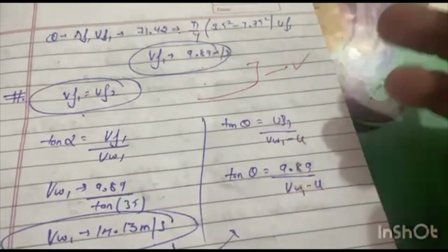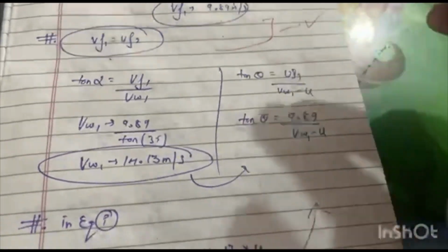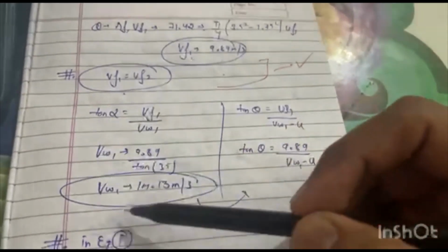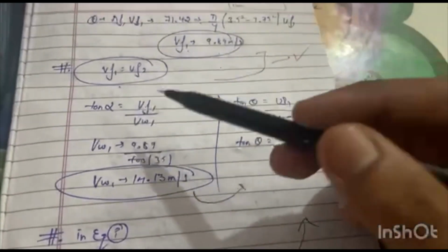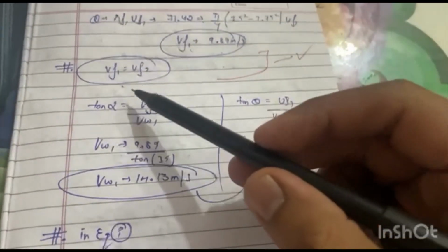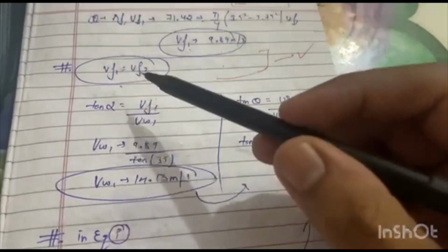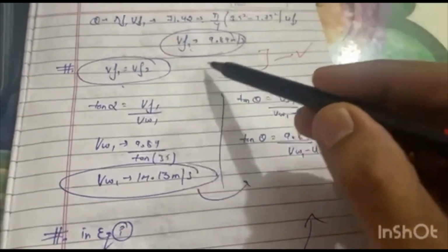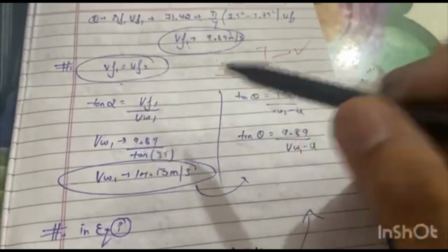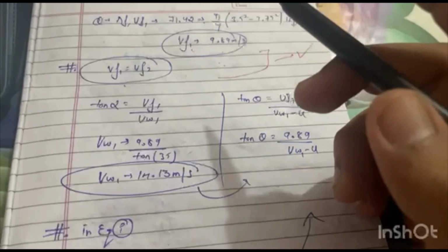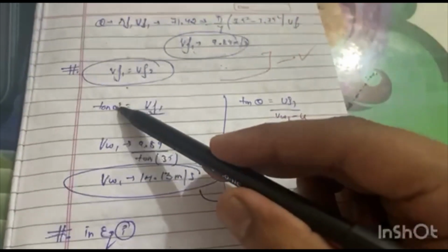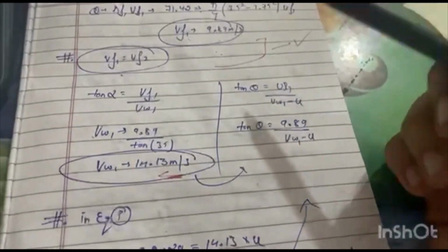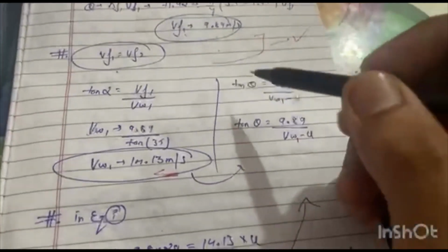अब VF1 आ गया तो हम इनलेट एंगल पे रख देंगे। वहां से हम निकाल लेंगे VW1, tan अल्फा लगा के, VF1 अपॉन VW1, हमने यहाँ से निकाल लिया। VW1 हमें पता नहीं है, ओके। तो अल्फा तो हमें पता है, अल्फा उन्होंने गिवन में दे रखा 35, यहाँ से VW1 आ गया, ओके। इसके अंदर वाले ट्राइंगल में हम एक और ये लगाएंगे,